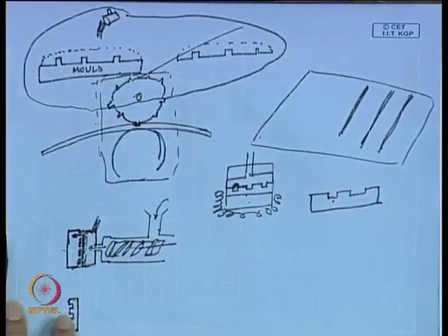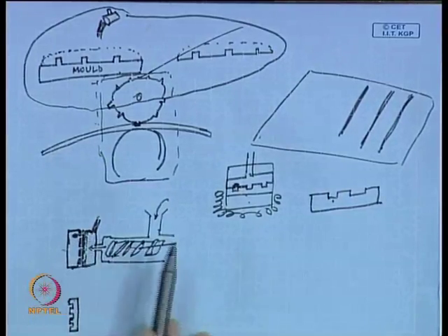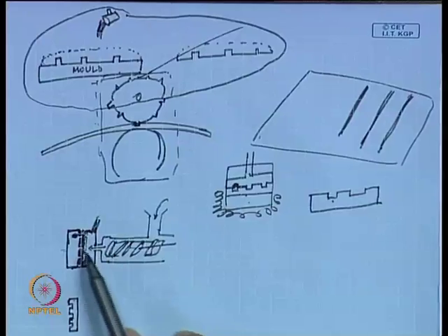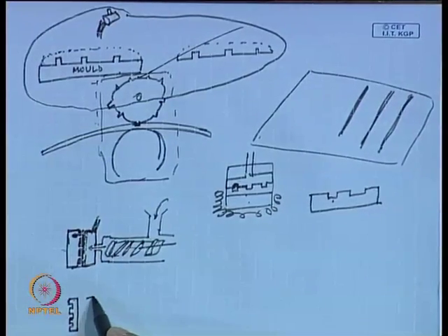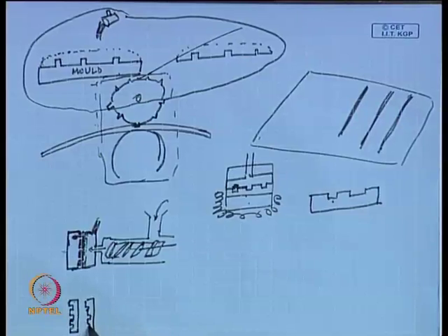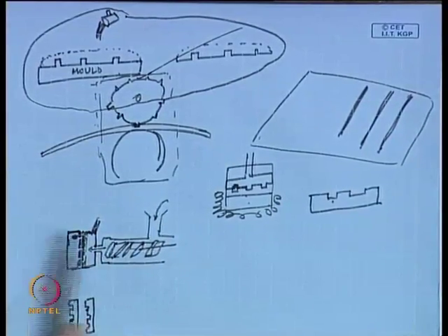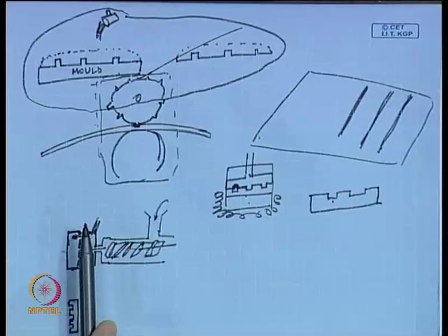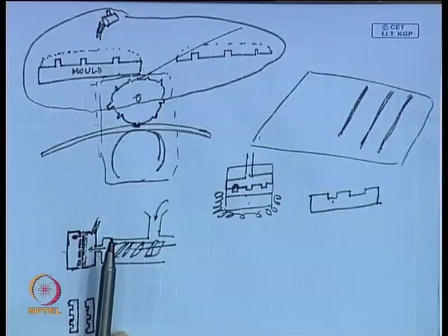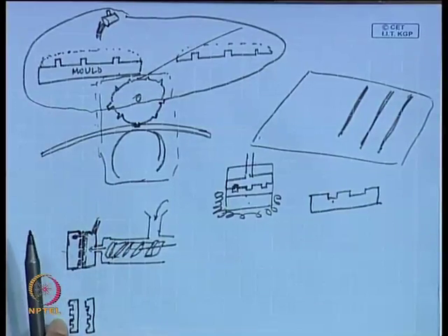Again, this block goes back and fits to this jig. The next layer is formed, and then you collect another one. So, this would be serial production. Basically you have this jig which is moving back and forth, and continuously polymer is supplied through this hopper. Of course, it is arranged that way. The time it takes to come back, the time it stays there, and the time it goes back is sufficient for this polymer to spread through all the places, and thus you get a perfect device.